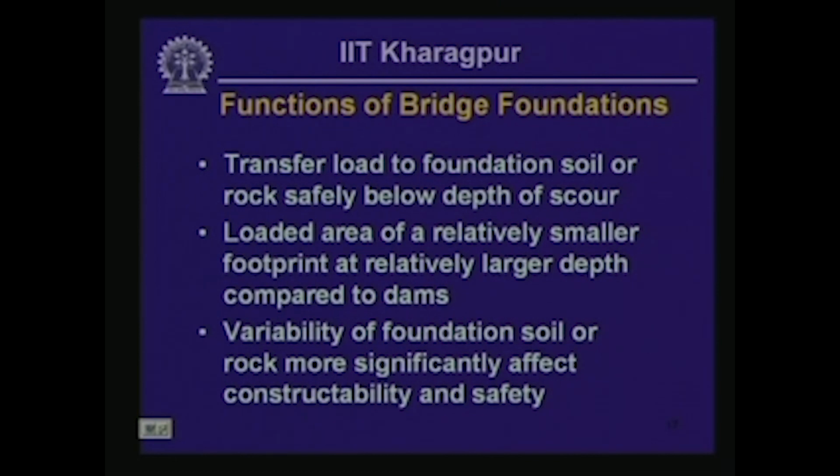So, the considerations here are essentially the same as we did in case of dam foundations. The only thing that you need to consider in addition is that the loads are transferred within a relatively confined, smaller area to a larger depth. As a result, the bridge foundation is affected more significantly because of heterogeneity in soil and rock.